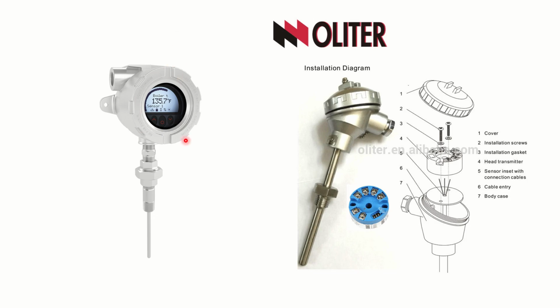Now whenever you see such a type of platform, you might be 90% sure that this is a HART sensor, because you can see here there are certain buttons through which you can make local changes in the program. This is the display and from where the switches may come. Now be sure that even if some particular sensor has such housing, that may not be a HART enabled sensor, but still in most of the cases it is a HART enabled sensor.